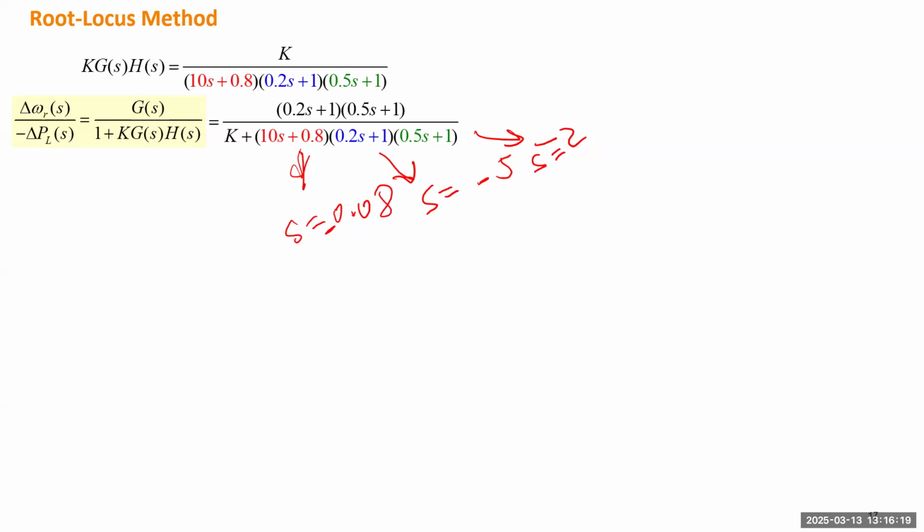Okay. If the open loop transfer function has any zeros, they show up here. But for this case, there's no zero. But if you assume there is some zero, we put it as s plus z. That zero will appear here, right? And when k increases to infinite, the open loop transfer function poles are not important anymore, but the open loop transfer function zeros will become poles.